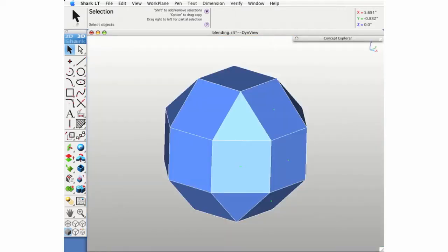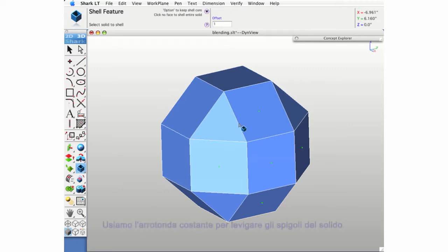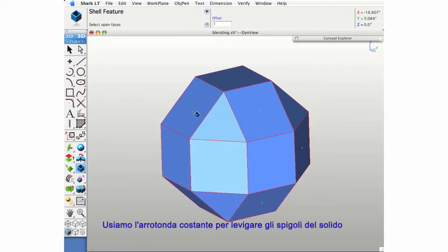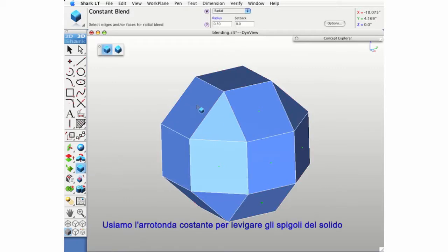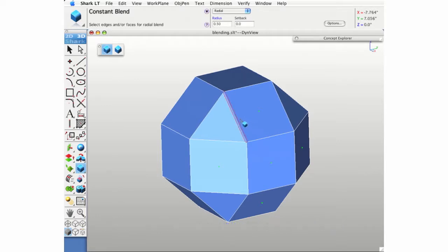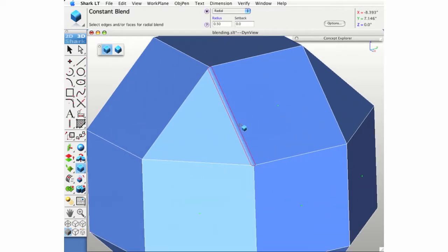First, let's blend a single edge. We'll blend this edge up on top at 1 inch. Let's select the edge, go over to our blend tool, and select this edge. You can see we're smart enough to understand that we have a relationship between these two faces, and the capping blend is interfacing with the two bottom faces on top and the two faces on this side as well.